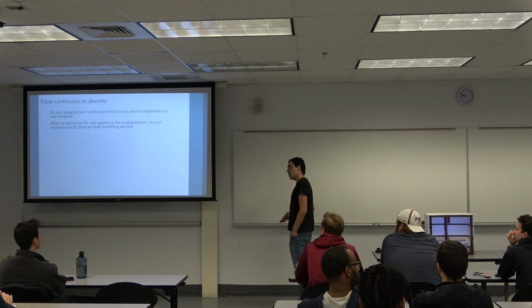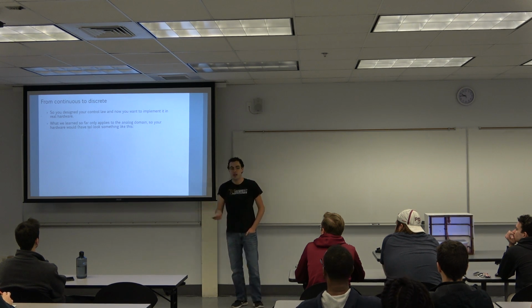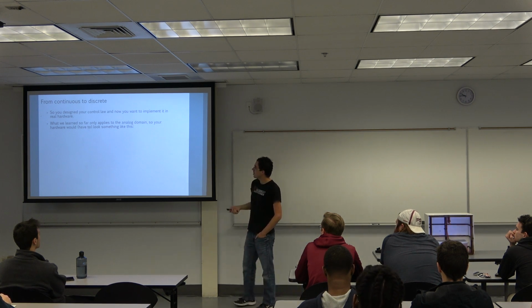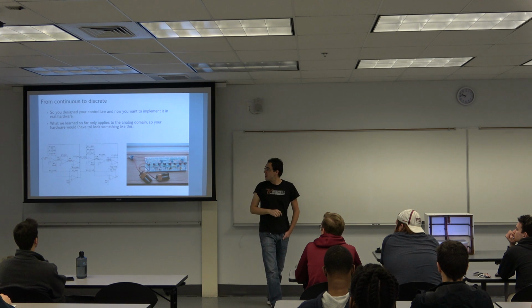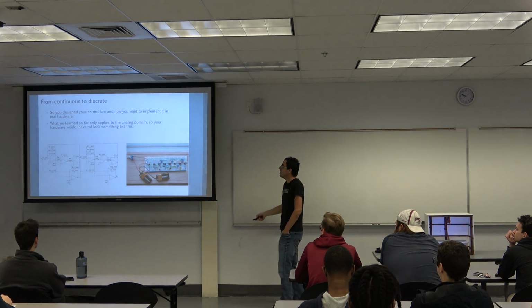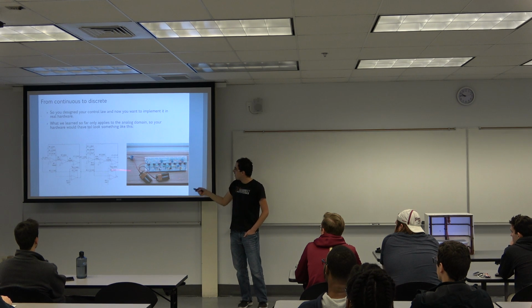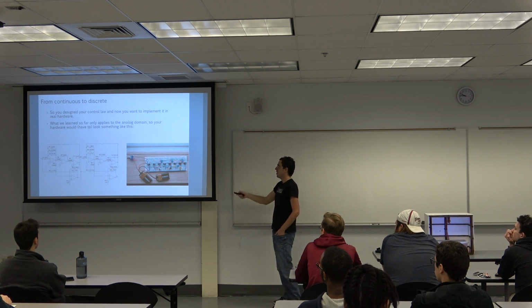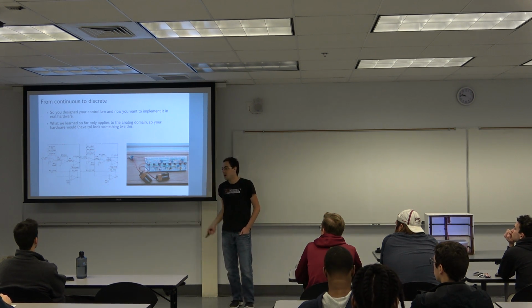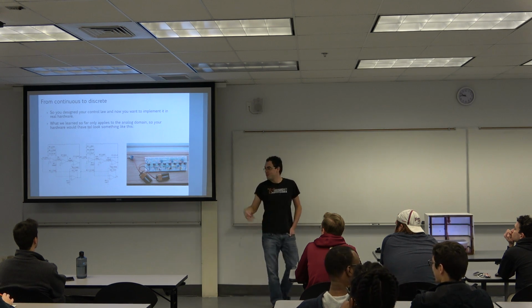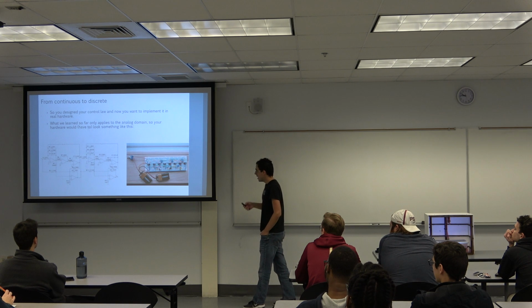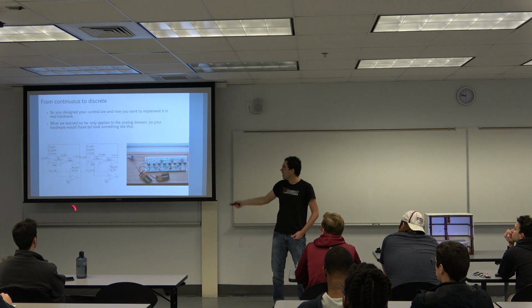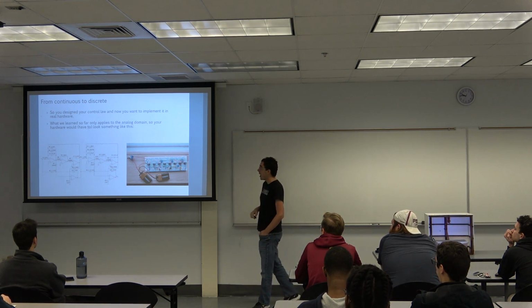But with the things you learned so far, which are the S domain analysis, you can only build a subset of controllers. And the subset needs to lie in the analog domain, which means that if you were to build an electronic circuit, it would have to look like this. So it's a set of analog amplifiers. Each amplifier does a role, integrating or differentiating, and the values of the resistors correspond to the cutoff frequencies of the filters and everything. And of course, if you want to change the characteristics of your controller, you're going to have to change the values of the components, which is not very handy.